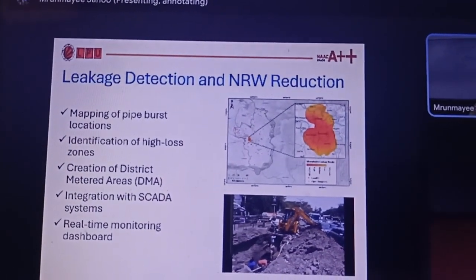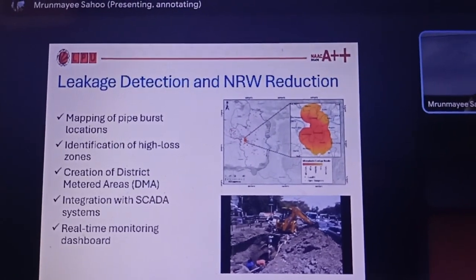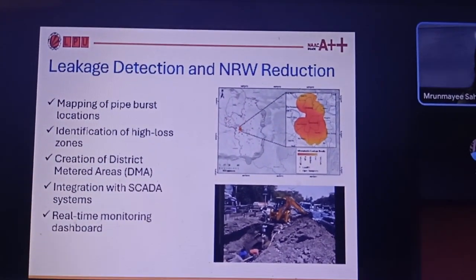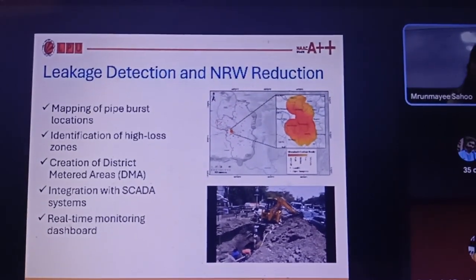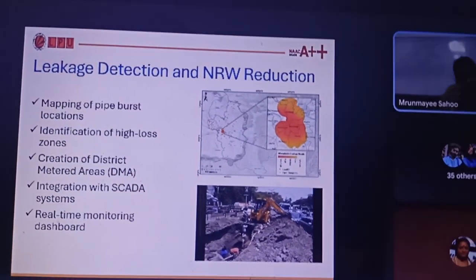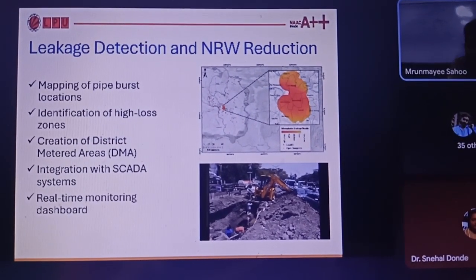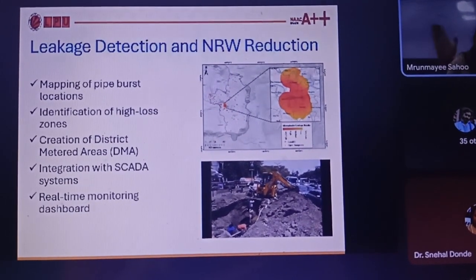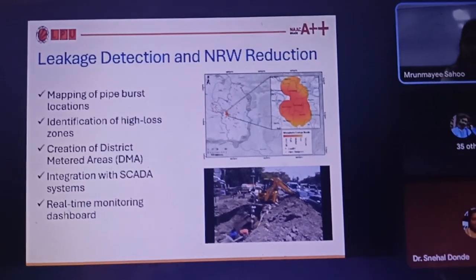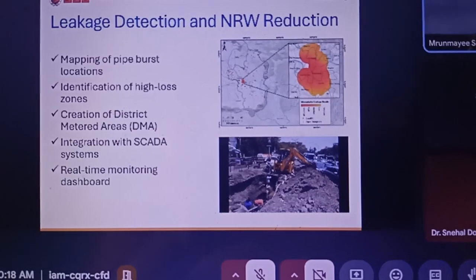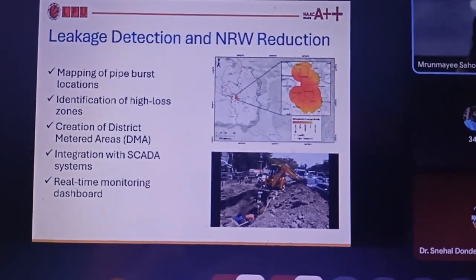At the same time, if you open your GIS, ArcGIS integrated with EPANET or WaterGEMS, you fetch the real-time data and can see the flow of water in that particular area, even below the soil. Below the soil, it will be a jet leakage. It's a very small burst, but a jet of water will be coming out. Those kinds of leaks you can detect instantaneously, and you can go for renovation or checking.